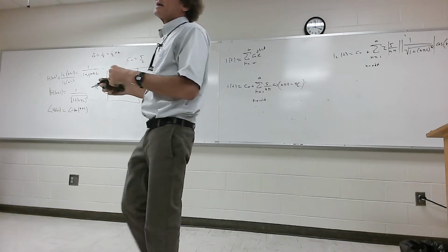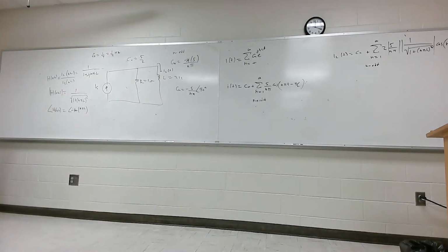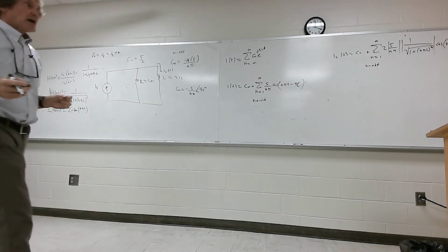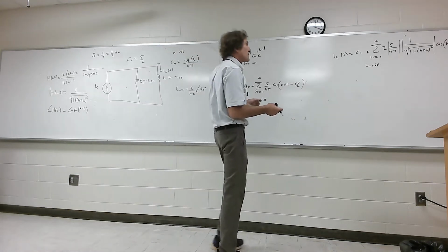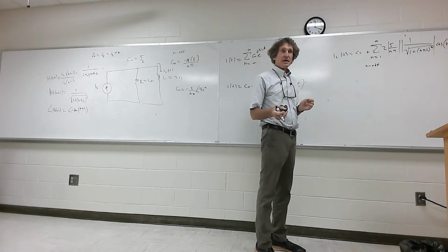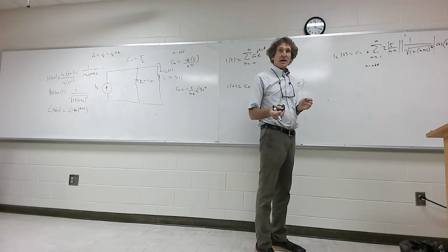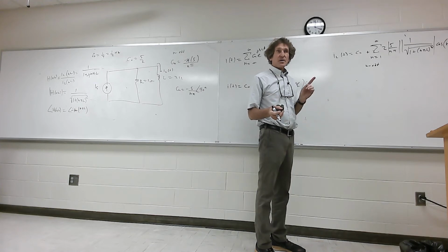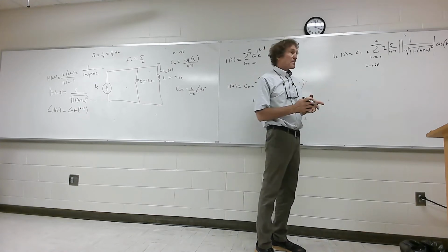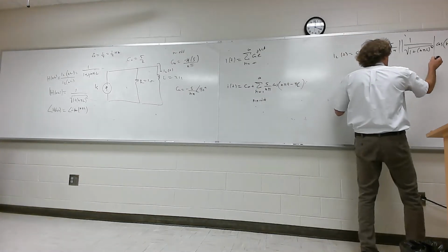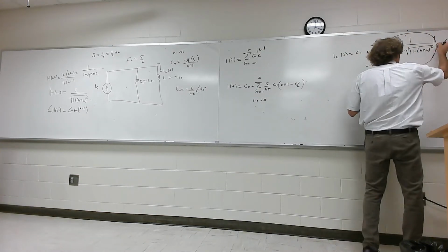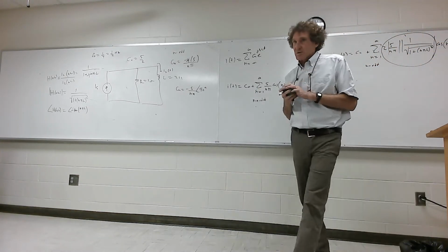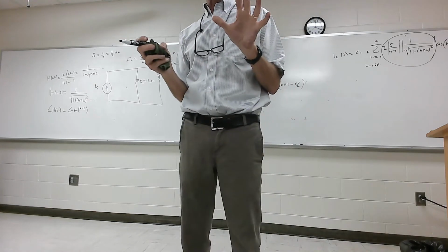And if I ask you, this is a typical question I would ask. I would want to know the value of the current of the 5th harmonic. Do y'all hear me? How do you get that? The value of the current in the load at the 5th harmonic. It's this evaluated at n equal 5. That's just magnitude. Y'all follow me on that, class?